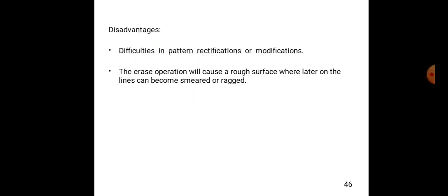Once we make the design, modification or rectification is not possible in ink designing. The erase operation will cause a rough surface where later on the lines can become smeared or ragged. So that is the main difficulty of ink drawing.